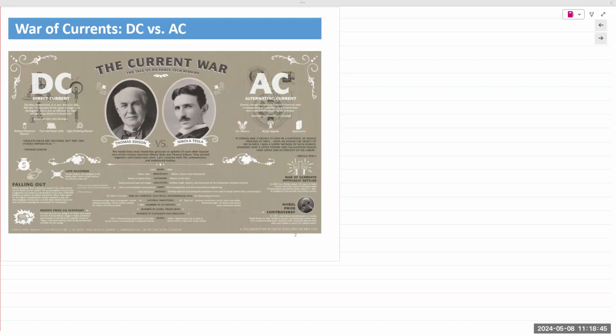Edison's engineers and salespeople had a hard time selling DC power and DC generation because it had limitations. It needed special lines, it needed special equipment, it couldn't be transmitted successfully for long distances. Whereas AC can be transmitted over long distances. Using transformers, you can step up the voltage of AC to tens of thousands of volts and send it over long distances. The point of increasing the levels is that anything transmitted over long distances loses power, and if the voltage is high enough, the power loss at the other end is not significant. That's the reason. And when it reaches the destination, you can use transformers again to step down the voltages.